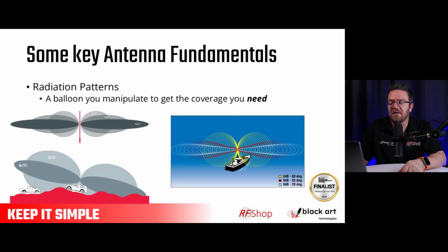All right. Now, as I mentioned in the previous slide, if you look at some key antenna fundamentals, the radiation patterns, I did a video on this actually many moons ago. Low gain can be beneficial, high gain can be beneficial. You need to make the right choice. You don't just go for high gain because you can. You need to look at what you need for coverage.